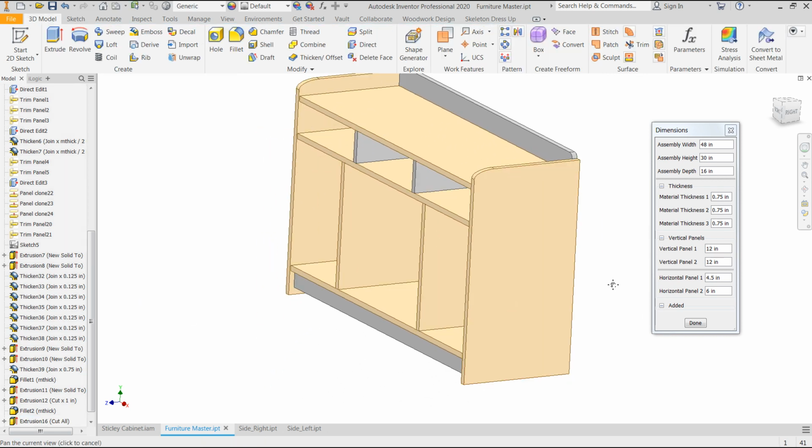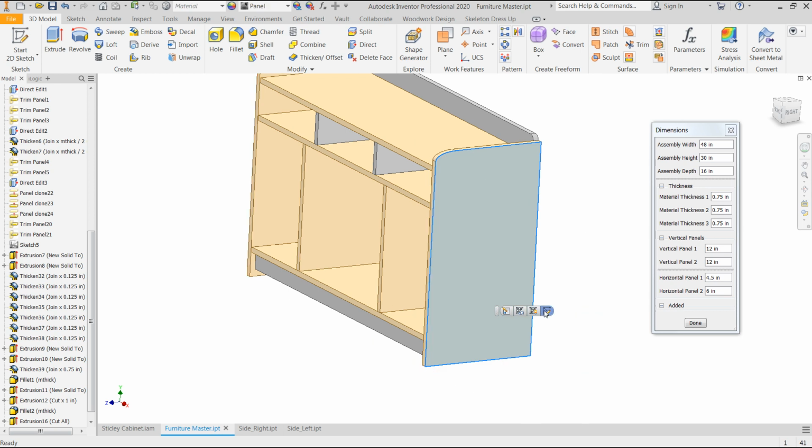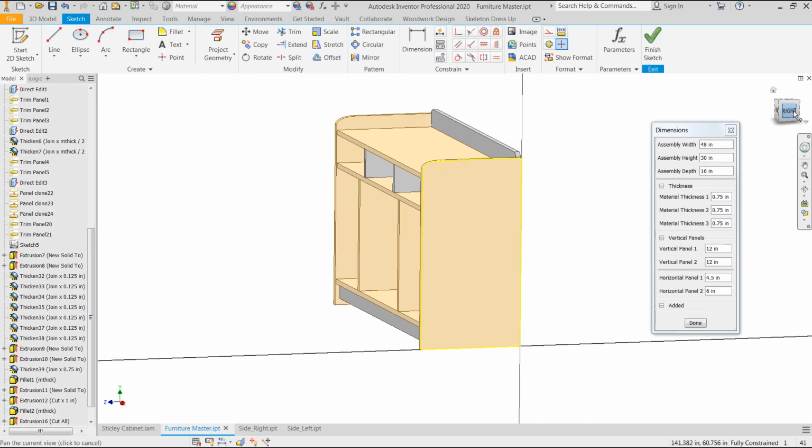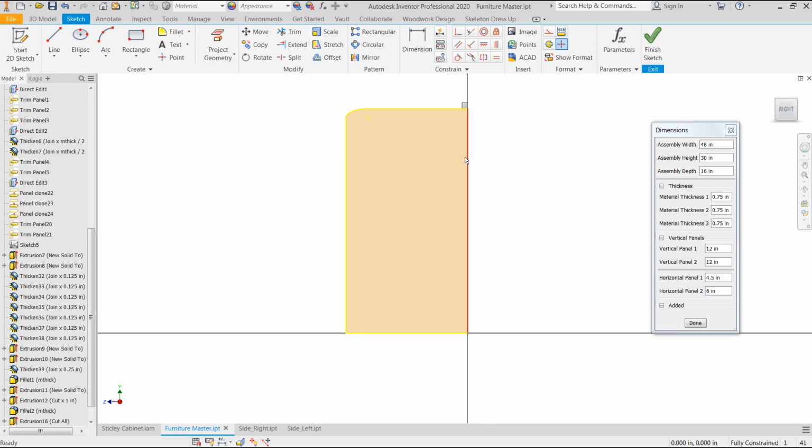And that's done. Let's go ahead, sketch again on the bottom. And I create multiple sketches. I don't like applying a sketch here and in the same sketch tool doing the cutout here and the cutout there. The reason is I'm complicating my sketches, and also maybe I want to turn one feature off without turning the other one off. Also, for diagnostic testing, if there is a problem, it'll be easier to delete one or suppress one to verify what might have possibly caused a problem.